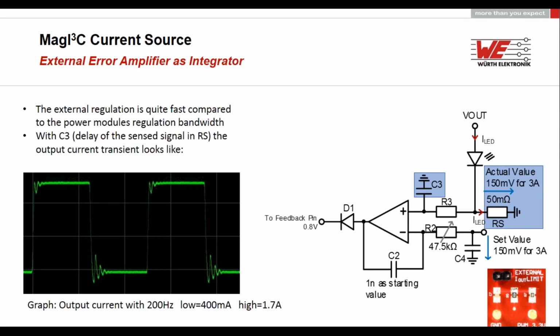But the regulation is quite fast, and if we want to keep the speed of the error amplifier regulation, we have another option: to remove C3. R3 and C3 are in this schematic because if you have an output capacitor on the reference design or an additional output capacitor, and you have an open circuit, you will have the maximum adjusted voltage, for example, the 14.4 volts.